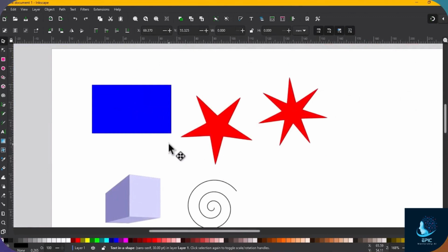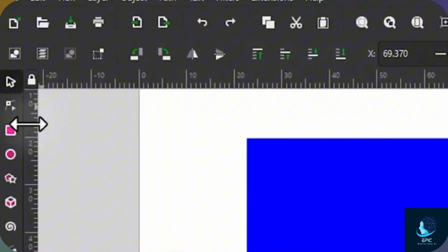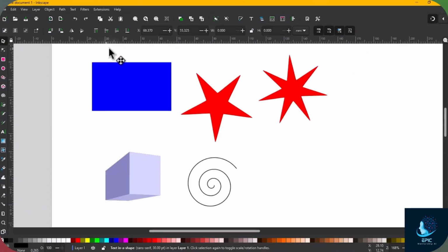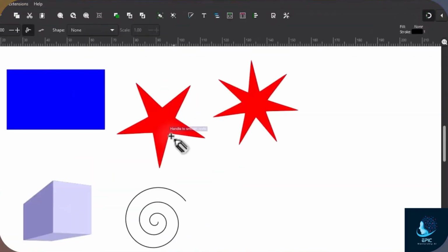Inkscape provides several graphic aids and snappings. Two rulers on top and on the left show the cursor position with the measurement unit fixed for the document. From the top right corner, you can set all the snapping options. You can enable or disable all the snappings, or turn specific snappings on or off.